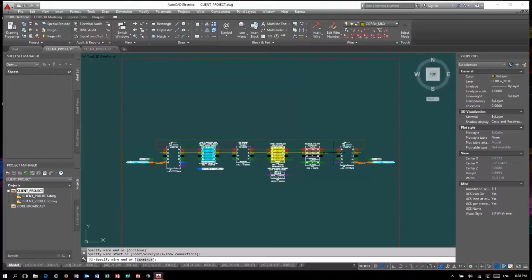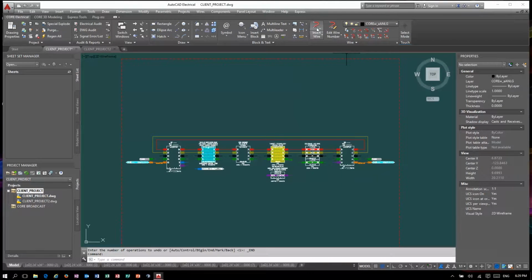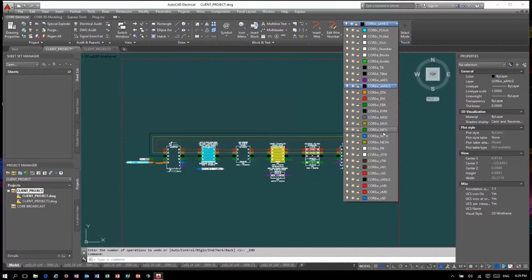You've probably wondered by now, why have we decided to use all of these various colors and connector styles? For two specific reasons. One focused on the user, the other on system design. For the user, it's easier to identify the signal types via colors. The other allows the ElectricalWireRunList tool to identify the various signal types within the drawing. It will then warn you about accidental connections or mismatches between signal types.